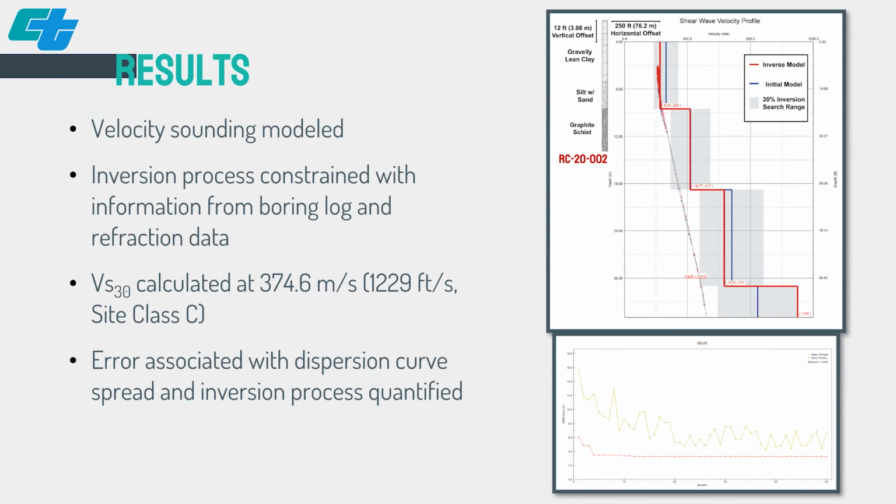Below the model is a plot of misfit or RMS error at each iteration of the inversion. It can be seen that the genetic algorithm used for the inversion is making adjustments to the initial model in an attempt to decrease the normalized RMS error between observed and initial model dispersion curve. But after 4 iterations, the fitness plateaus, indicating that the initial model was not too far off.